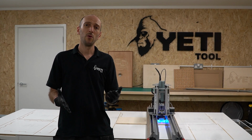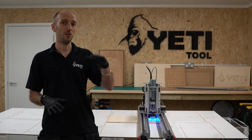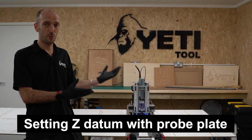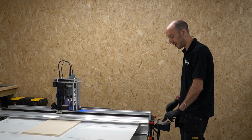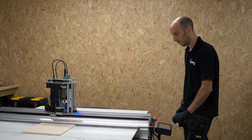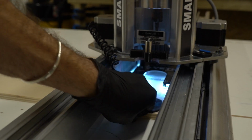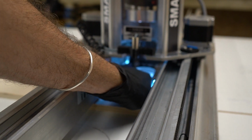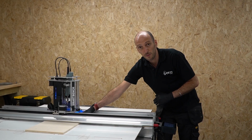In this example, we've set the job file's datum to be at the top surface of the stock. So let's now use the Pro plate to set SmartBench's working datum to be on the top surface of the stock. I'll navigate the Z head over the top surface of the stock. I'll pull out the Pro plate and insert the Pro plate underneath the center of the tool. And I will position the tool to be a few millimeters above the Pro plate.